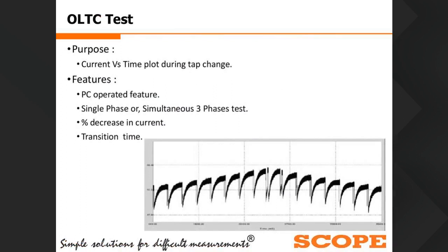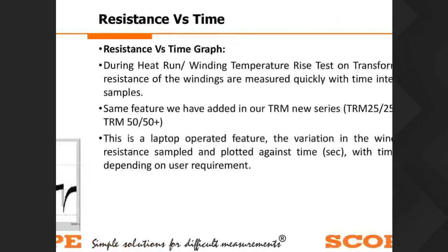So here I will conclude the OLTC test. That is, with the help of the OLTC test through our instrument, we will plot and take all the data, that is transition time, percentage decrease in current, and the current versus time graph, with the help of our TRM instrument.